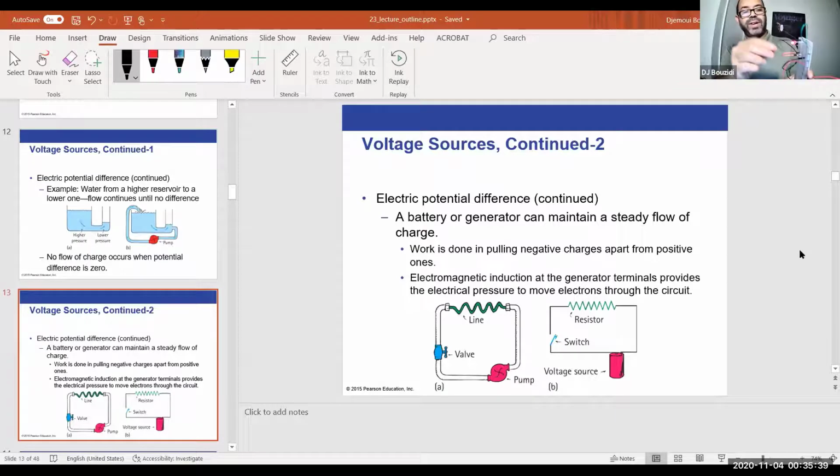Just to illustrate the point, if I reverse, I'm going to change only this one in here. If I reverse the diode and put the long leg on the opposite side of the battery, this should kill any current in the circuit. Okay, and it's not lighting at all. But if I reverse it again, it's going to come back on. So this is basically a simple circuit that involves only two items, a resistor and a diode, an LED in this case.